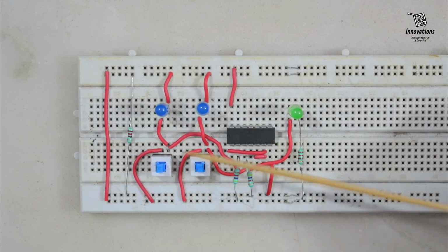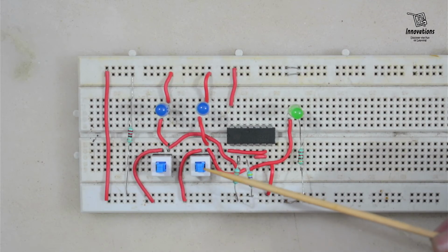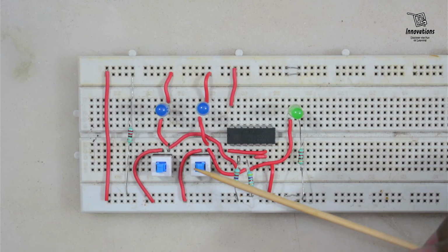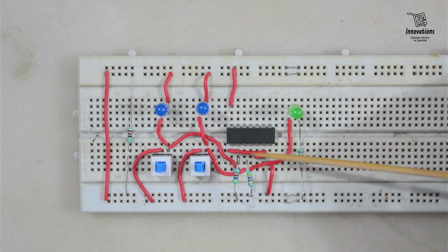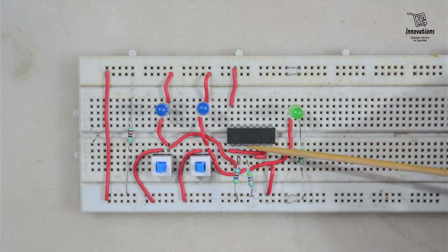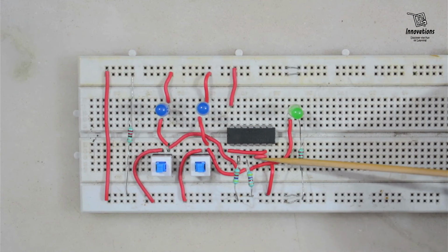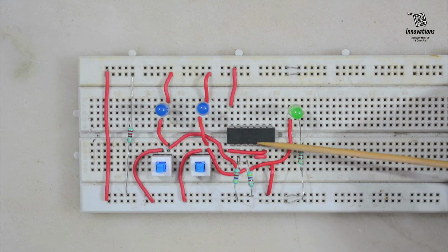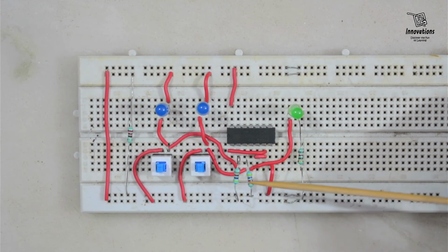So here is the circuit of an OR gate using a NOR gate IC 7402. We have implemented a 2-input OR gate here. So here are the two inputs, and these two are the input status indicators that are connected with these switches, and we have fed the two inputs to pin number 2 and 3 of the first NOR gate segment, and the output of the first NOR gate segment, pin number 1, is then sent to pin number 5 and 6. Pin number 5 and 6 are interconnected using a jumper loop, and the output from the second segment NOR gate, pin number 4, is then connected to the output status LED. And now, as we are providing two inputs to two different pins, we have used two separate pull down resistances in this circuit. Now we will give the power supply and check it.